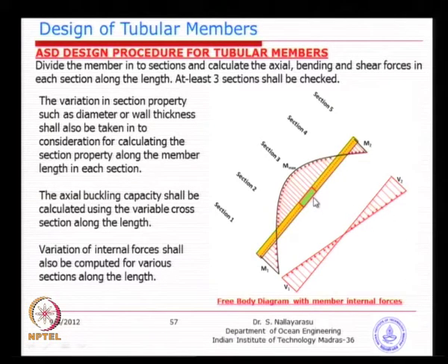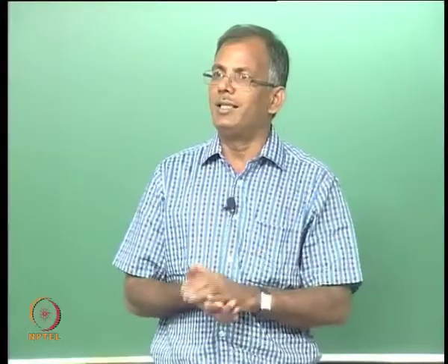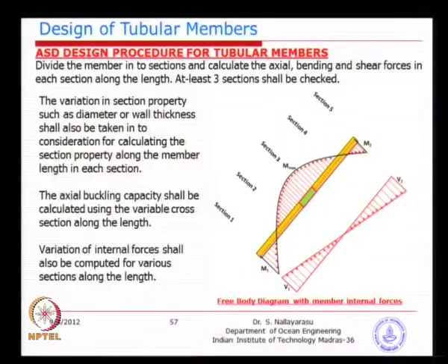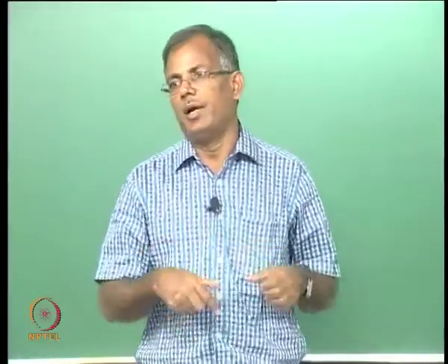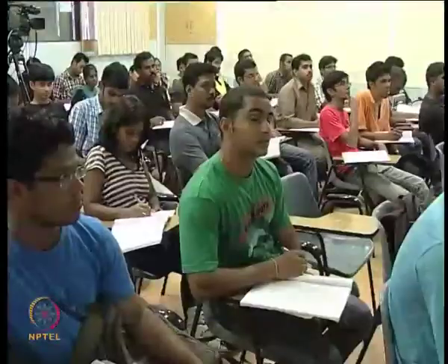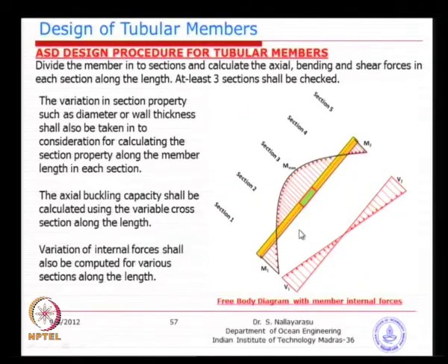You see this picture, at the center we have a different color, meaning a slightly increased thickness because there may be a member coming and connecting somewhere in that location. So, you may have variable cross sections, changing moment of inertia, changing cross sectional area, and changing bending moment and shear force diagrams. All your design calculations need to be verified at every section that has a critical combination of section property and moment and forces.